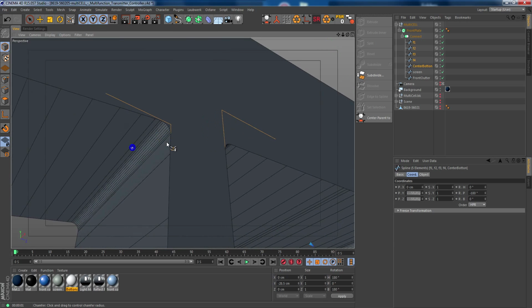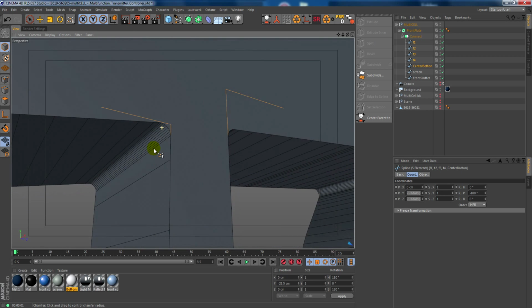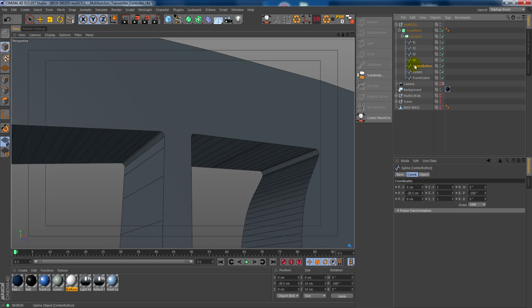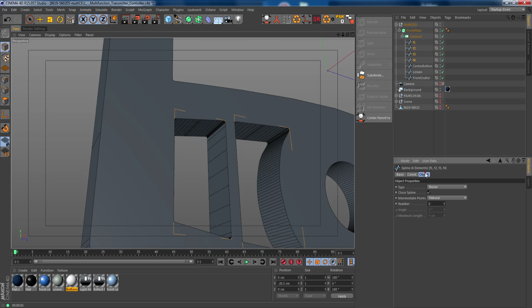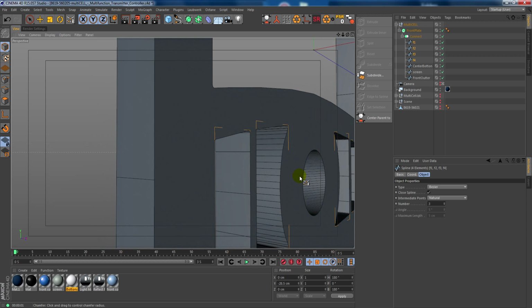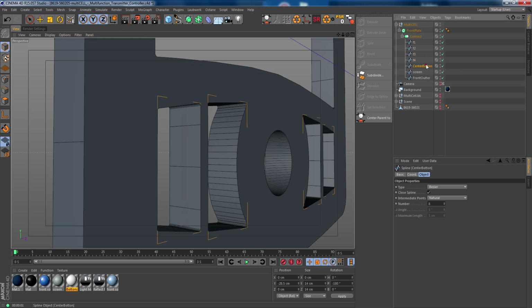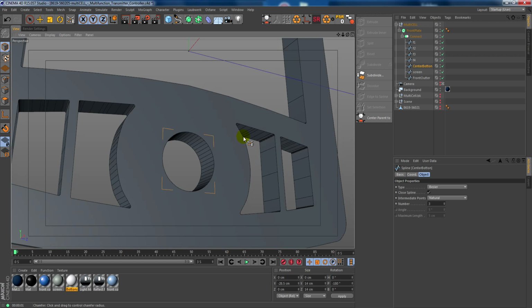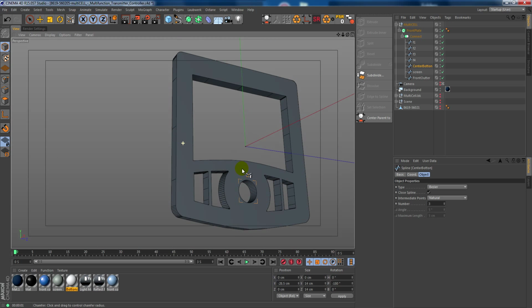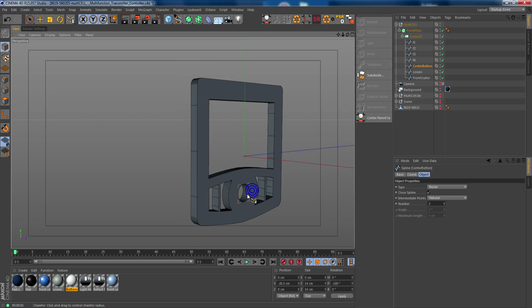One of the things we do want to do is again just optimize these points. You see we've got too many polygons here, so let's just go ahead and we can do this. Let's just do the buttons and not the center one. Come over to points here, and I'm going to put these down to 3. So we actually don't lose any quality there whatsoever. And again, I'm going to come to the center one and just do the same for that. Change that to 3. So it's probably still quite high, but I'm only working with this one model, so I don't really need to worry too much about the poly count.